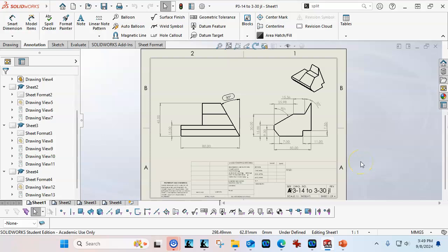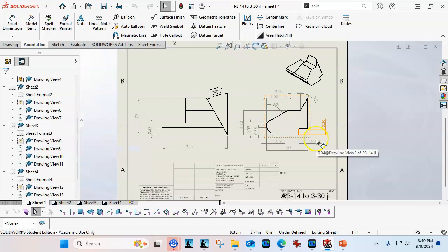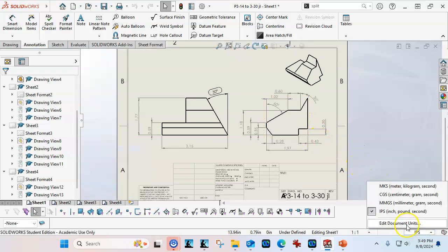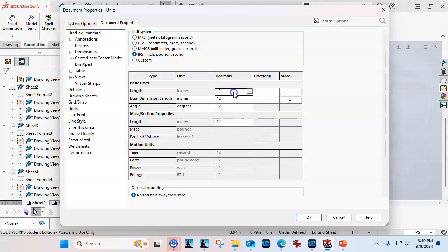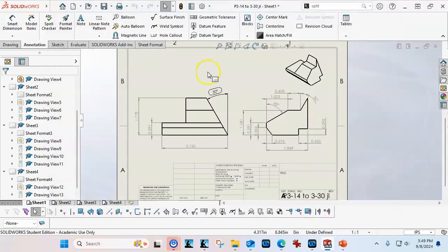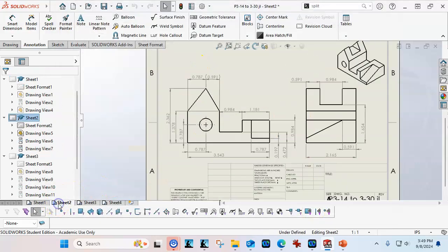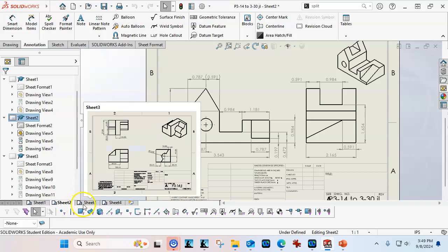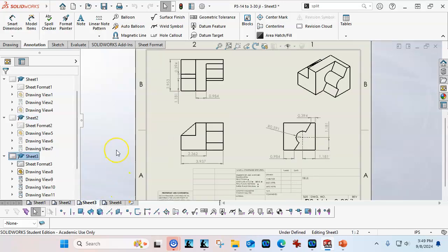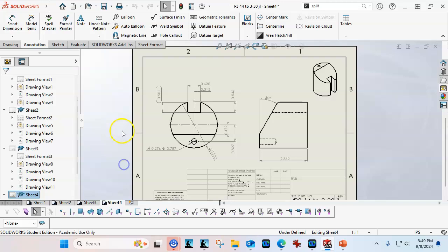dimensions, thinking about tolerancing. Also, are we going to build this in metric, or is it going to someplace that uses inches? We can switch it back to inch. If we need to switch to 3 decimal places, which in most cases we're going to want to go to 3 decimal places. I don't have any dual dimensions, but if I did, I would want to just go ahead and make sure that that's in millimeters. All right, so that gives me those. We're looking for places that I am having the interference or the crossover from the metric to inch.